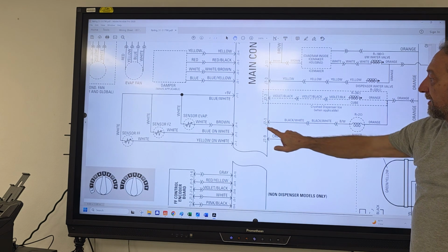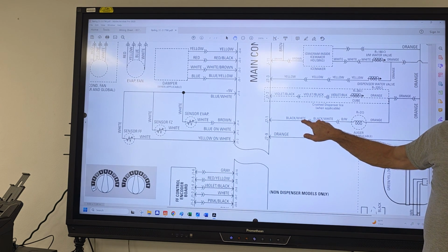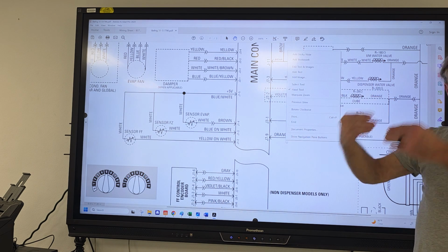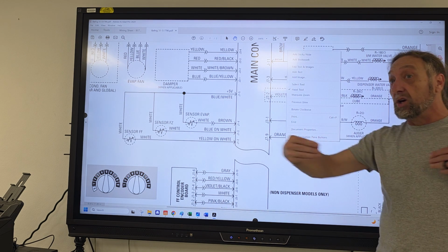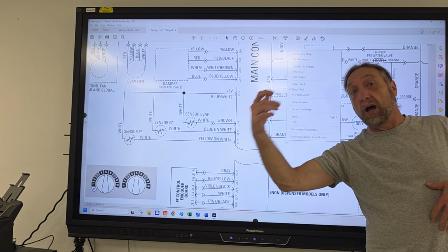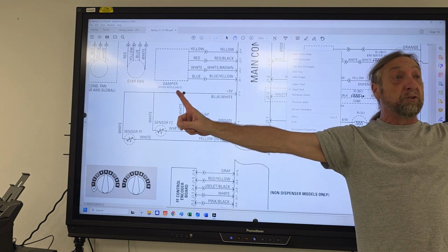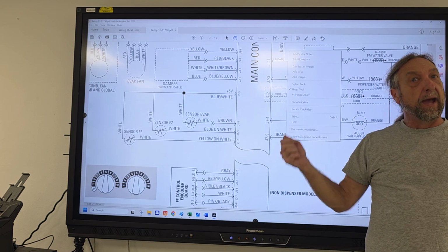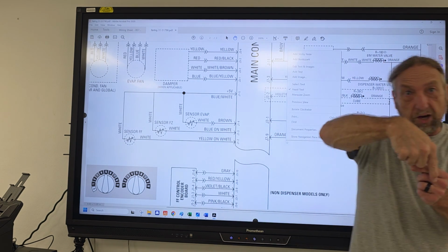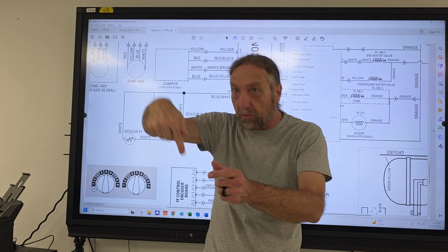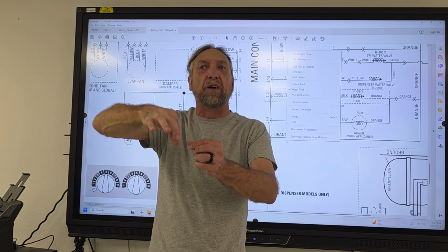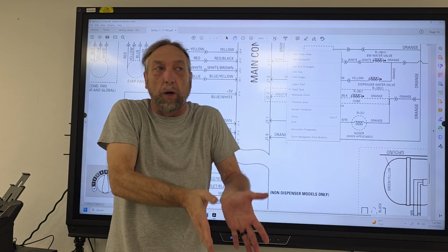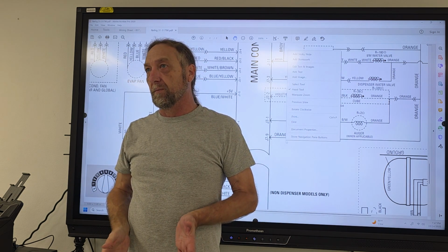Where's J71? Is this one? What color wire is that? Black and white. Black with white, because J79 is orange. So I look at the plug, and I look at all the wires on there, and if it's number 1, it's on the end, one or the other. I'm going to look for a black wire with white on it, and that's how I know, okay, that's number 1, so the next one's 2, 3, 4. Oh, there's no wire on 5, but 6, 7 there are. That's how I figure out where my connectors are on the board.